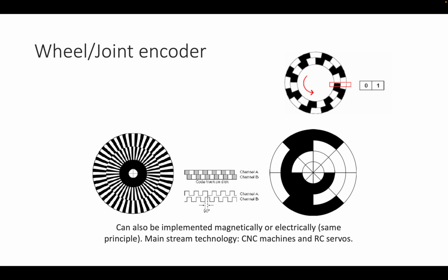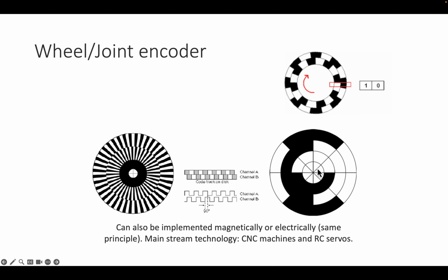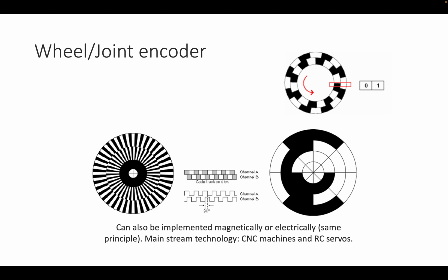Now, this introduces an important concept, absolute and relative measurements. The absolute measurement gives me the actual position. The relative measurement gives me only the speed or the relative motion at which something happens. This is the same with the accelerometer that you've just seen. It's a relative measurement. It's the acceleration, which is the derivative of speed, which is the derivative of actual motion. And the gyroscope, or the rate gyroscope, which is the derivative of the absolute orientation.